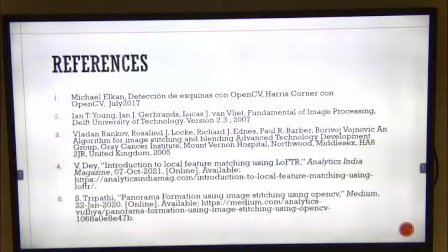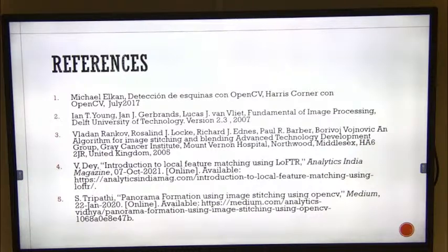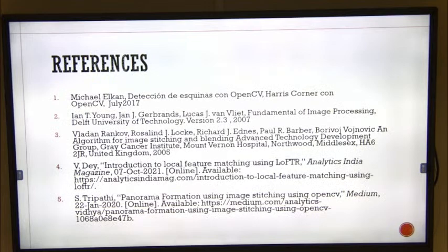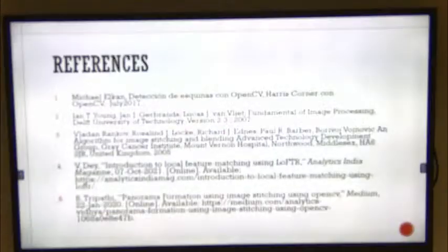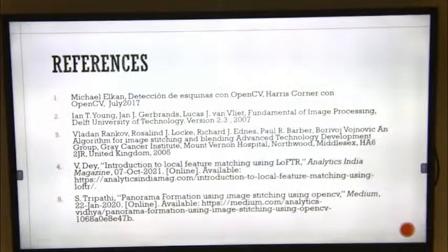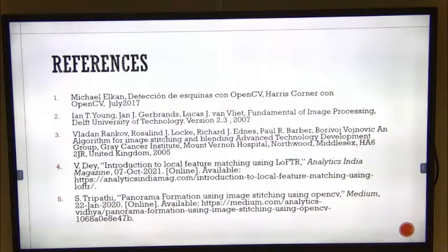Yeah, that's a good question. When we were taking the pictures, we were using a tripod with a camera mounted on it. The way that we did it was practically visual. We had the horizontal angle of the camera set on the tripod so it wasn't moving around. And we were estimating the overlapping percentage that we needed for the pictures using the display of the camera. We were taking an array of pictures in what's called a snake pattern. We were going from the bottom, then from the top, then to the middle, then to the bottom when we were taking the set of pictures.